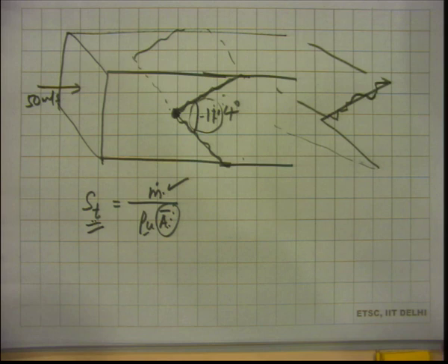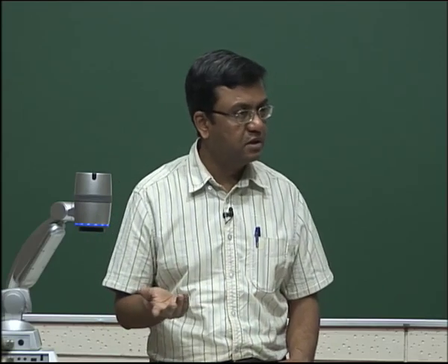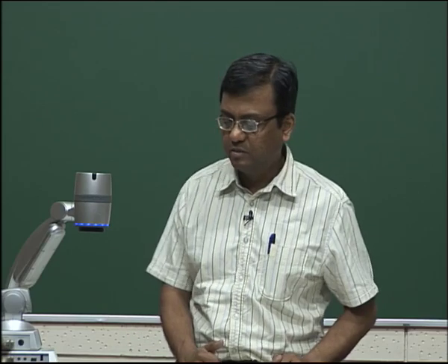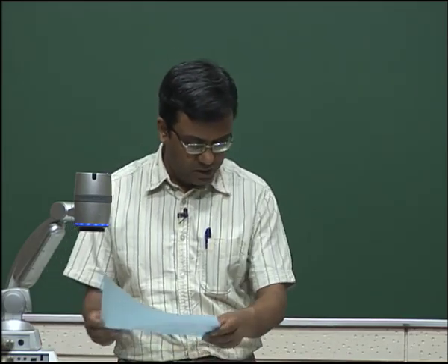We are not discussing actually turbulent flame stabilization in detail, but I just took one example. So there are other methods of stabilizing flames in various kinds of situations. Flame stabilization is an important issue because let's say in a gas turbine, if the flame doesn't get stabilized, if it moves, then there is a problem. There's a huge problem, right? You have to be able to stabilize it. So this is one situation.